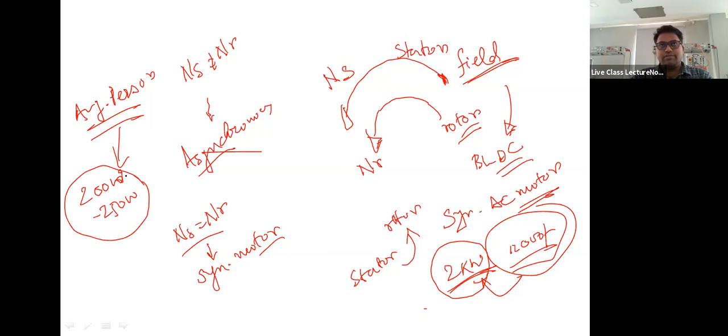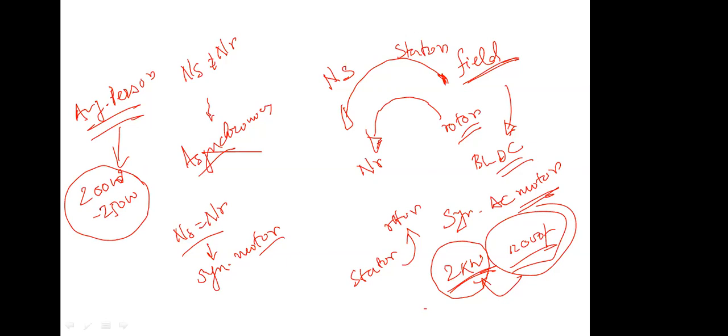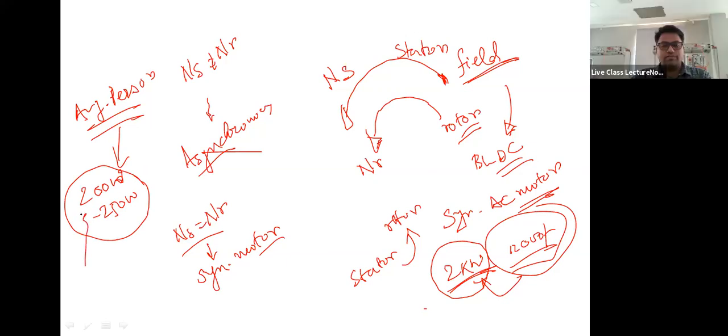If your electric vehicle is carrying only 200 watts of motor, you don't have to have a license for it. So that's a good convention: 200 watts per person. 200 watts per person times 5 persons will give you 1 kilowatt. And the weight of the auto, if you have to pull it, is hardly 80 to 100 kgs.